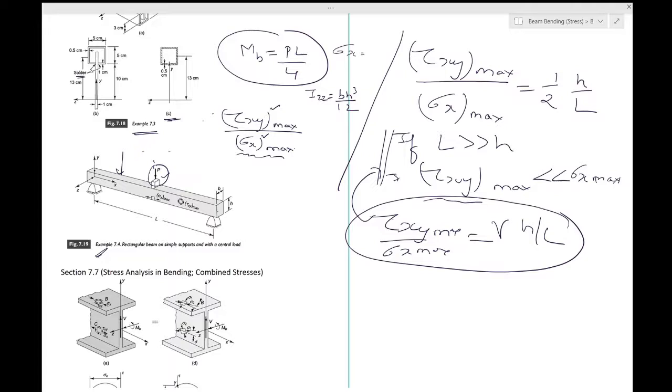If beams of other cross sectional shape are investigated, similar results apply. If it's not rectangular, say an I shape or an H shape, you will obtain a similar result. The factor of proportionality does however depend importantly on the shape of the section. So the factor of half can be as large as 3 or 4 for I beams, and then you will have to reconsider this particular part: if L is say 10 times greater than h, what would the other terms mean.